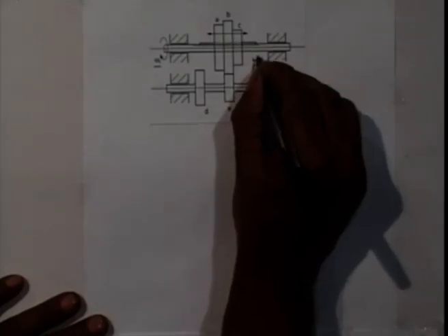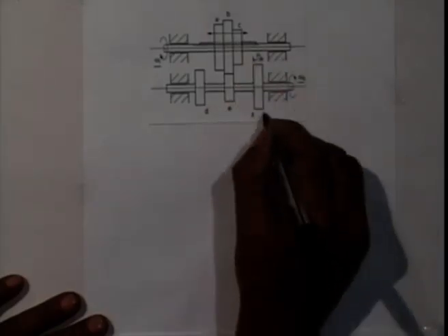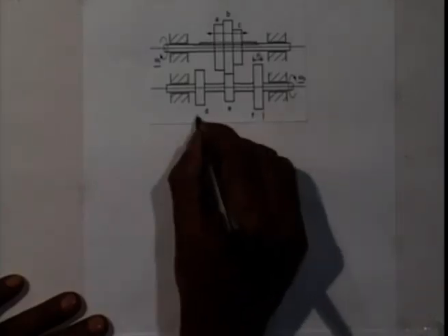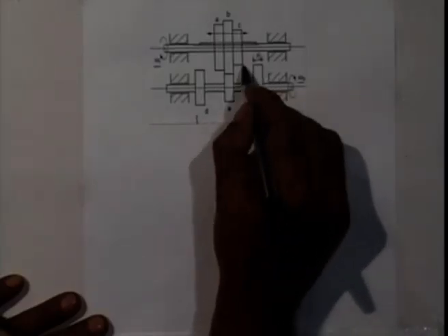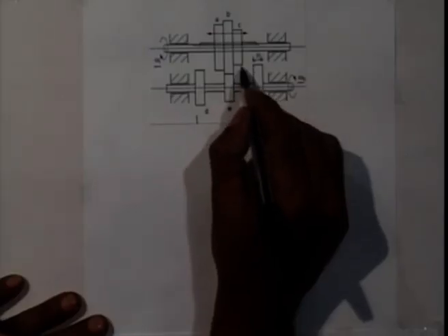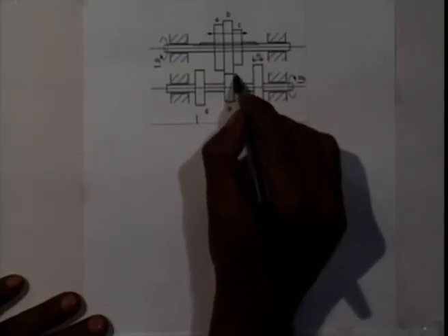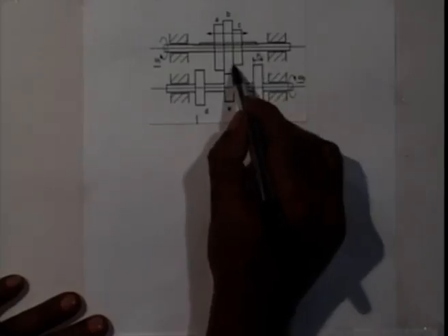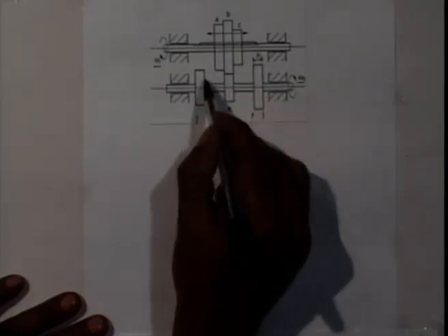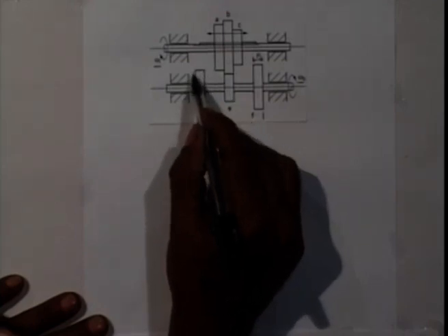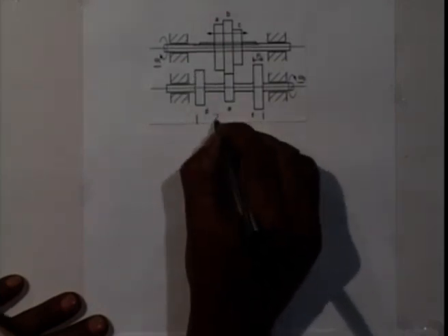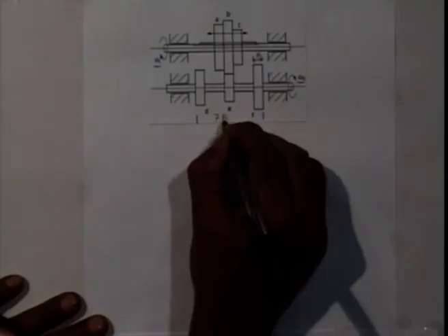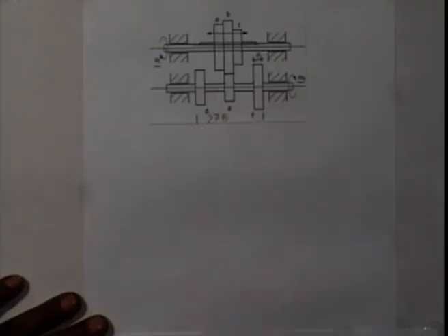So suppose the gear face widths of all these gears are the same and I call it B. If every gear has width B, then this total distance is B plus B, because for it to clear, that movement is B, and before it comes into engagement, B plus B plus B plus B plus B, again this gap must be B and B, so this whole distance becomes at least 7B. So it should be more than 7B.